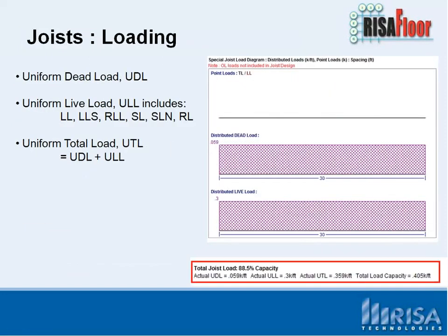Let's talk a little bit more about the joists here. So in RISAFloor, you can design joists. You can lay out joist girders, and you can lay out single steel joists. And the way RISAFloor takes that loading, we're going to apply a uniform area load to the entire model. And to analyze that joist, or to design that joist, what we're going to do is turn that area load into a distributed load per joist.